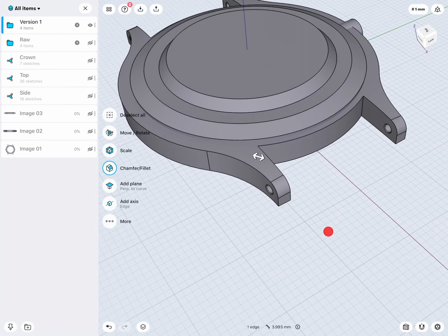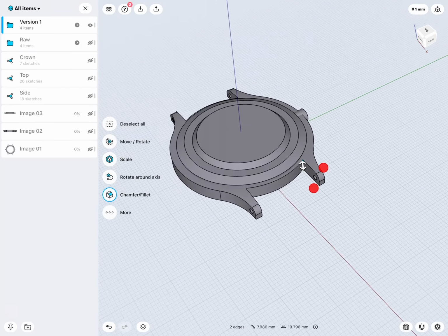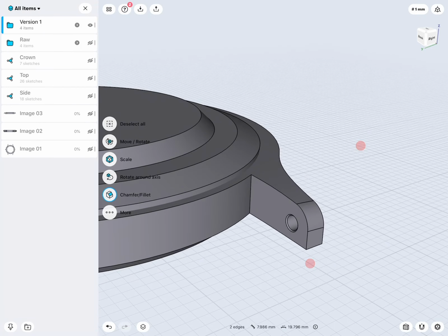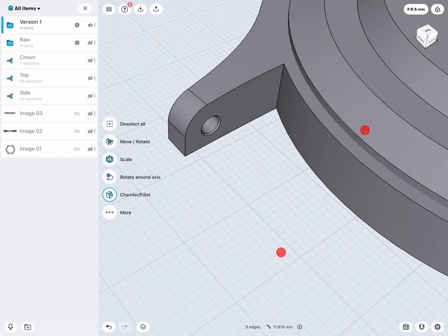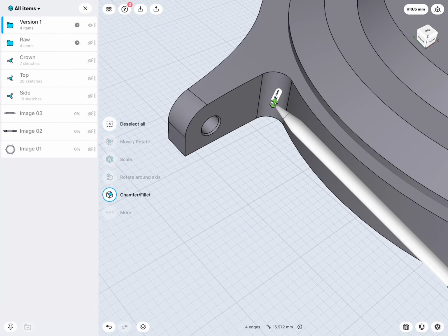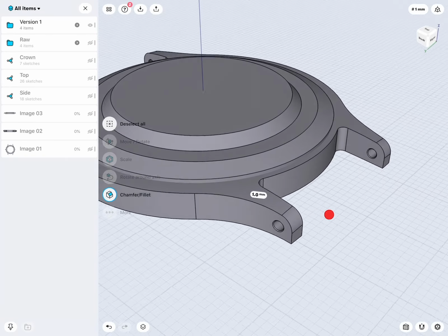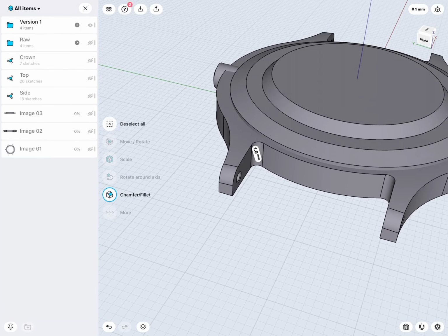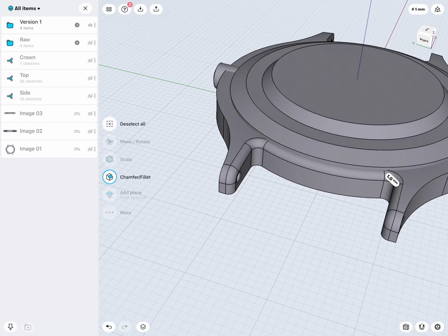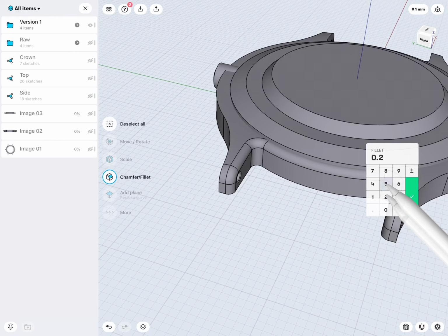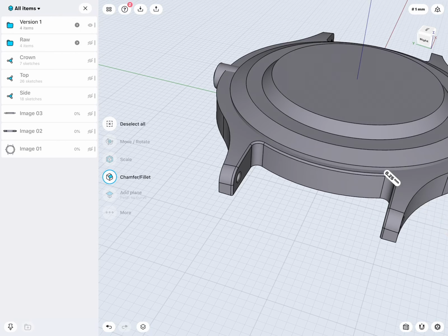Now the next step would be these inner corners, I can start rounding. One is good. Be careful with the values, because when we start adding another fillet over this edge, 1 is way too big, but 0.25, for example, is good.